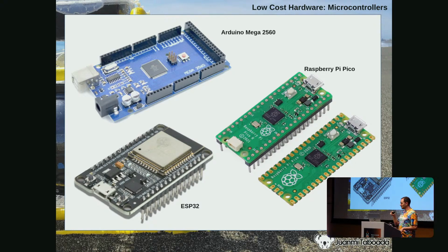Why did I have RAM problems? Because I needed to put into the buoy a library named MAVLink. It's a communication protocol that I used to talk with the submarine. The problem I was having is that even if I reduced the number of commands I was using and the commands the submarine was accepting, it still wasn't enough.